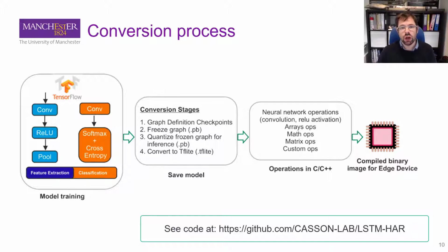So we do our deep machine learning on a computer, on a desktop, in exactly the same way as we always would. And then when we have that prototype, we convert it to a TensorFlow Lite representation of the same network. And then we look at optimizing that network, looking at how we can change the weight functions so that we can reduce the memory footprint and so on.